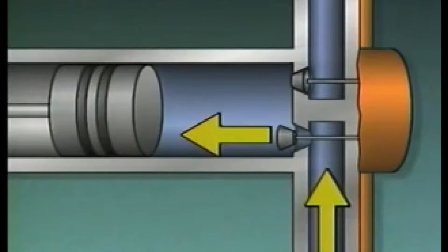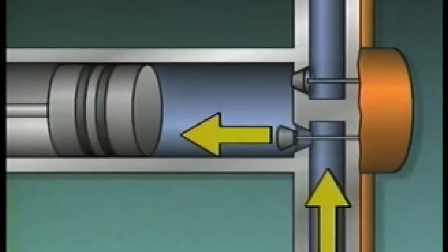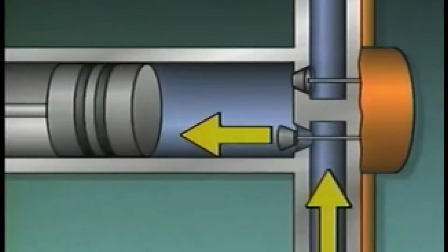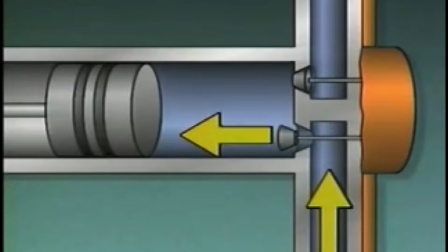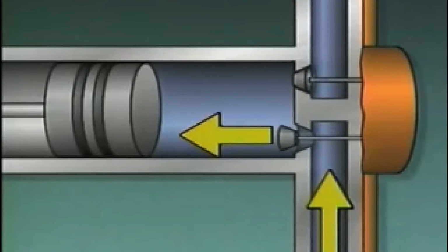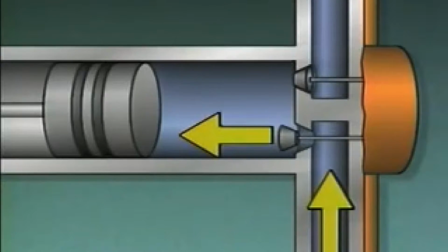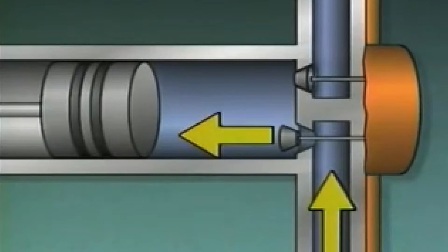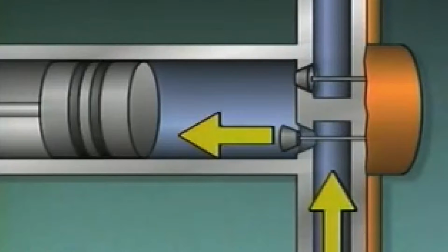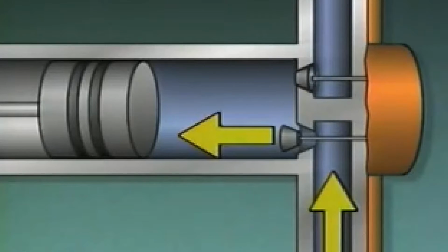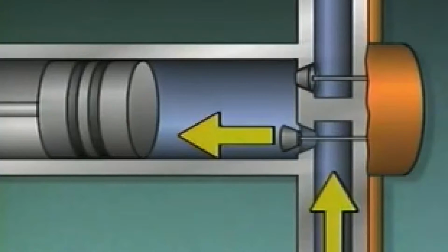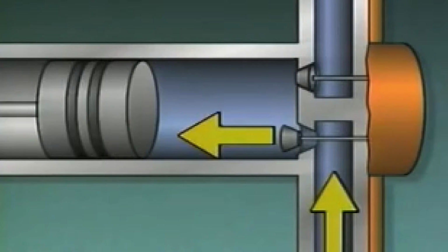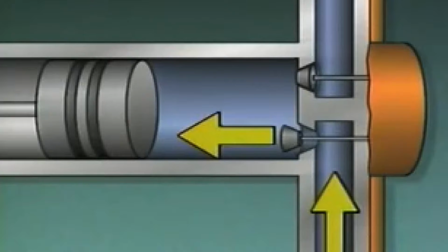So in this picture here, you see that the piston and connecting cylinder have moved backwards. This creates a void where it needs to be filled because low pressure system, pressure moves from high to low pressure. So that pulls both of the valves towards the cylinder, which closes the discharge valve and opens the suction valve. This allows fluid to come in and fill the void where the volume increased.